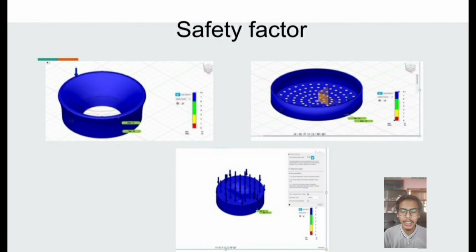We have put 3 critical designs to be analysed. In engineering, a factor of safety, also known as safety factor, expresses how much stronger a system is than it needs to be for an intended load. Safety factors are often calculated using detailed analysis because comprehensive testing is impractical on many projects, such as bridges and buildings, but the structure's ability to carry a load must be determined to a reasonable accuracy.